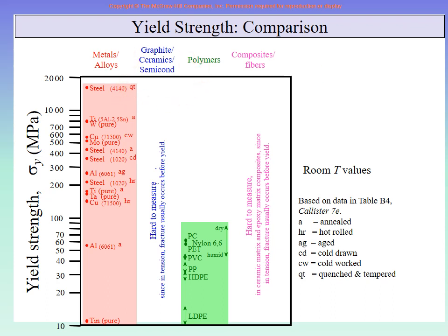Yield strength. Once again, if I ask you now, you have gone through the previous lecture, what is the yield strength? If you have to say one sentence, what will you say? Those of you who are saying that it is the point where the elastic deformation ends and where the plastic deformation begins, then you are right. It is the end of the elastic region. It is the beginning of the plastic region. So it means that yielding means that it has started to deform permanently.